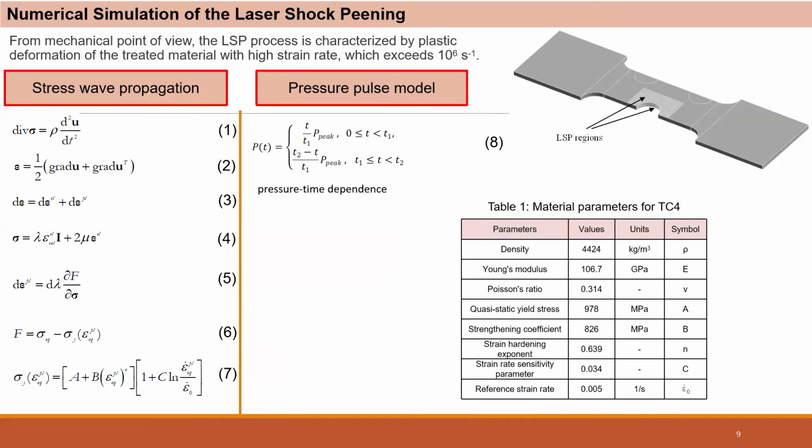In mathematical statement in equations, our numerical problem can be written as this. We solved this problem only as a mechanical problem without formulation of ablation of the material and plasma generation. The pressure pulse we received from PDV data and applied as a pressure on the surface of our specimens.